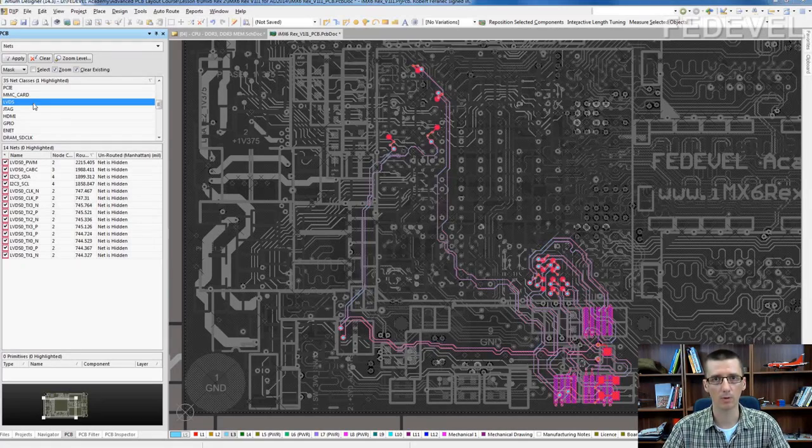And also, once you are doing the length matching, then even if the requirements are length matched to 100 mils, 50 mils, once you are drawing the tracks, it is not a problem to do the length matching within 10 mils. So just do it. And then you don't need to think about this.